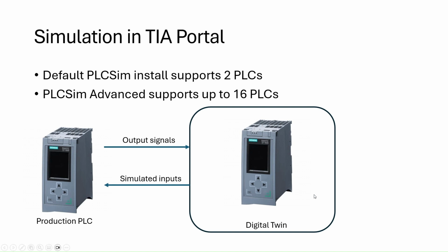And with that, you can use this PLC, you can add it to a library, and later on you could also use it for other projects. There's some standardization possible there, but with this, we are actually able to create our own digital twin without any other licenses or any other costs, and with a fast learning curve since you already know how to program a PLC.